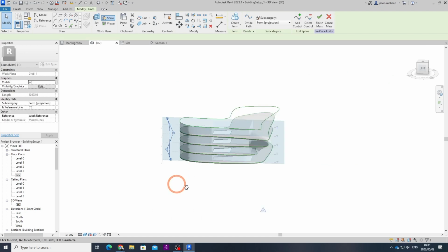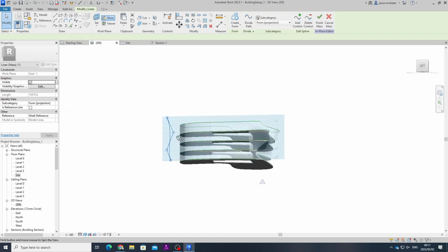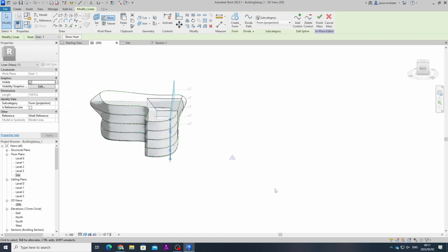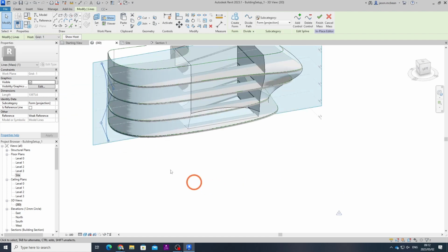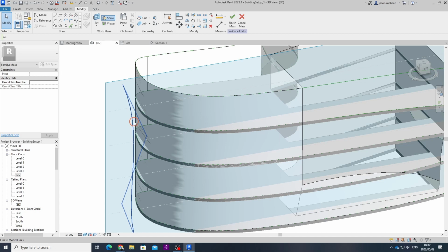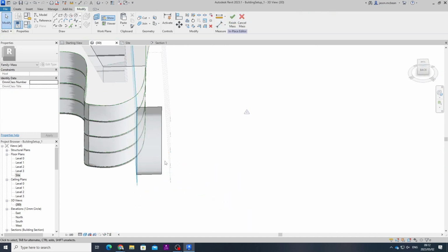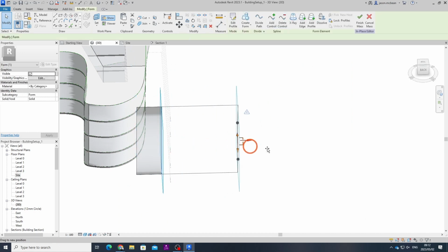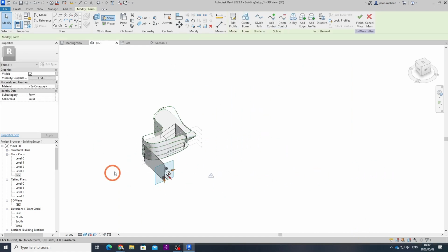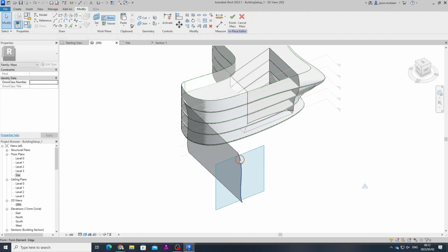So you see that I've created the shape that runs up here next to the building, but it's using my grid now as a work plane. So levels and grids become work planes now. It's quite clever. You can use reference lines to become grids as well. And I'll explain that. Now that this is the model line, I can literally click the form button and you'll see that it'll make an extrusion for me very quickly. So it'll do this for you. But that's not what I'm after. I want to do something a bit more. Just delete.